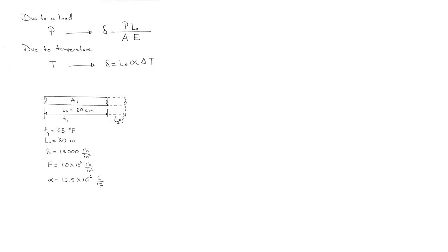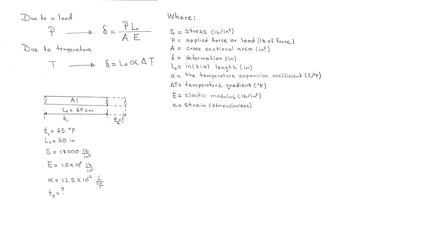Remember, our aim is to calculate the operating temperature of a heated rod that is allowed to deform up to its proportional elastic limit. To solve this problem, we need to find a relationship between temperature, proportional elastic stress, and deformation. The easiest way can be as follows. First, let's correlate stress and elongation and call this equation number 1. Now we need an equation describing elongation as a function of temperature gradient. Let's call this equation number 2.